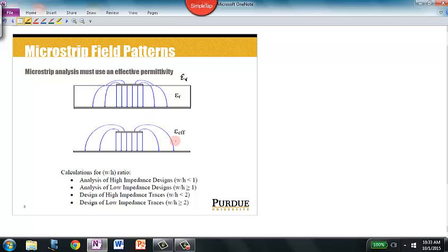What the effect is going to be is that the wavelength in a microstrip signal is going to be different than what we would normally calculate with the equations that we've already developed for microstrip T-lines. And we give it a new name. We give this wavelength for an electromagnetic wave in microstrip a new name. It's called the guide wavelength, and it's given the symbol lambda sub g. And it's calculated just by taking what the wavelength would be in free space.